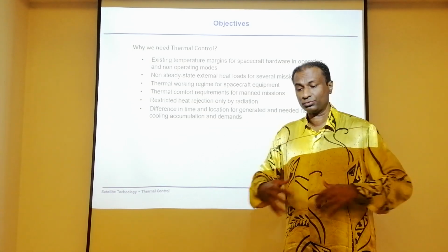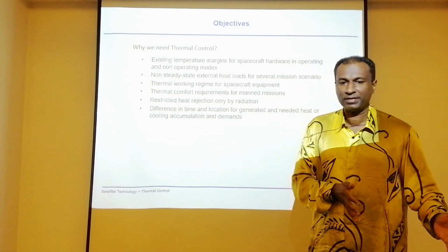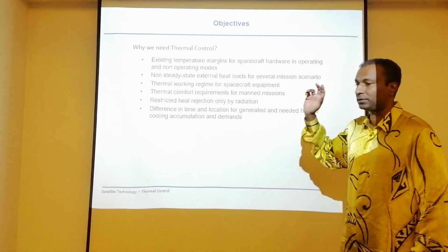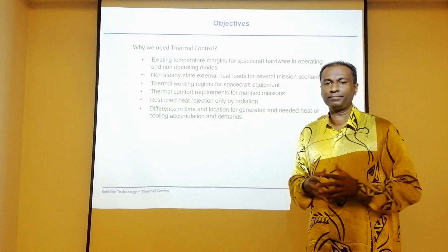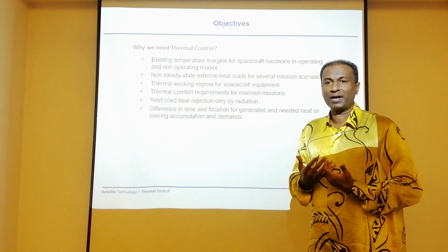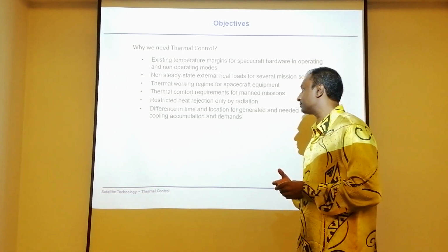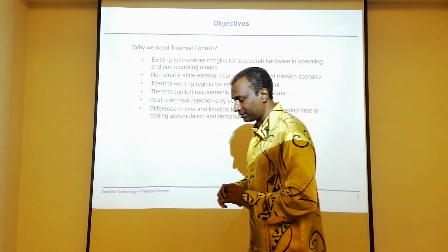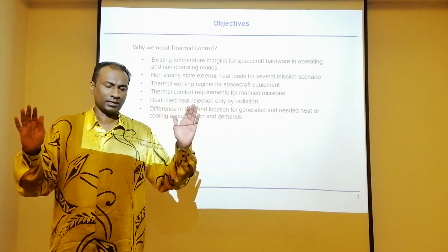So I need to devise all my thermal control techniques around that radiation endpoint. That is very important. It is not like other cooling systems, where you can cool a building, for example, using convection. It's easy because you have water, and it's no problem. But it's very challenging if you can only use radiation. That's very crucial. Then, as you can see, likewise we have two different phases: the sun phase and the eclipse phase.